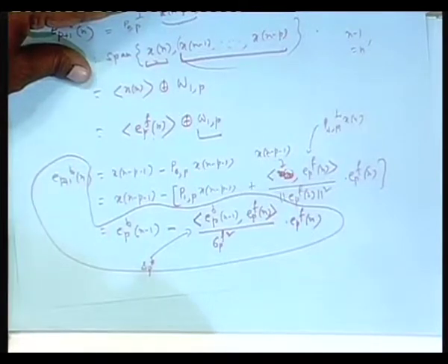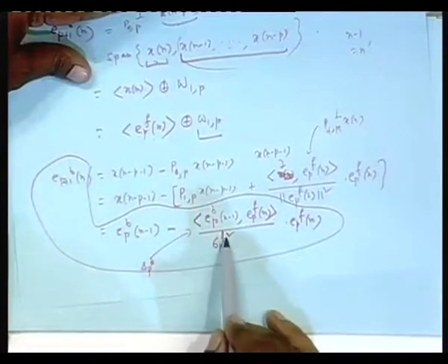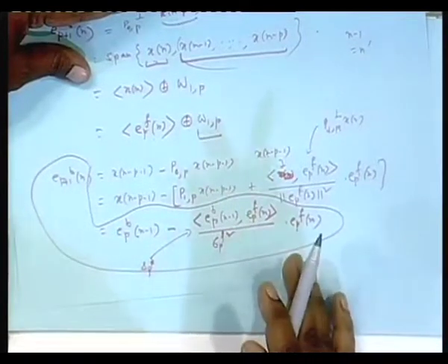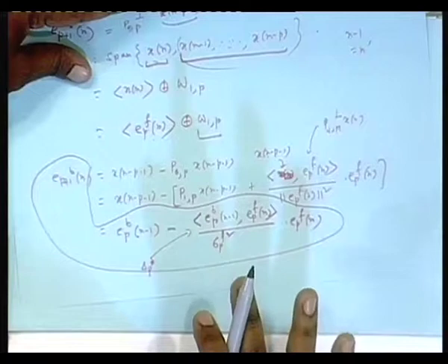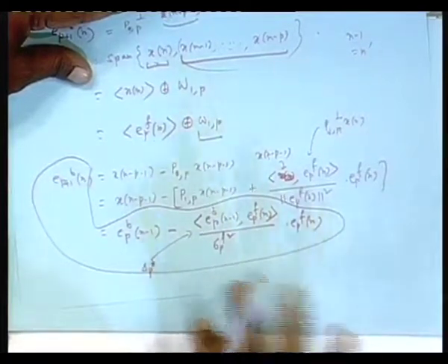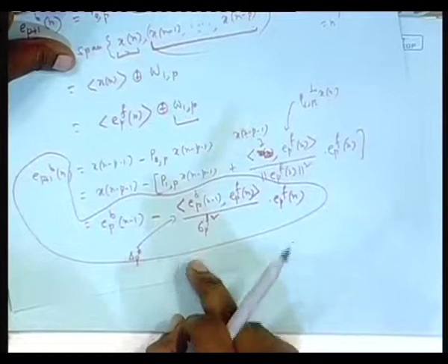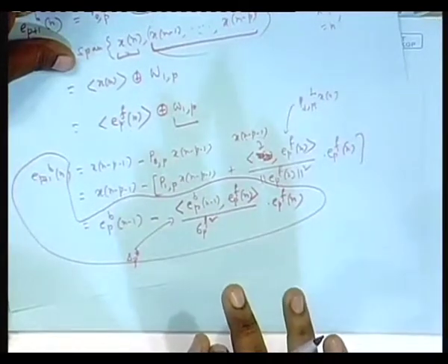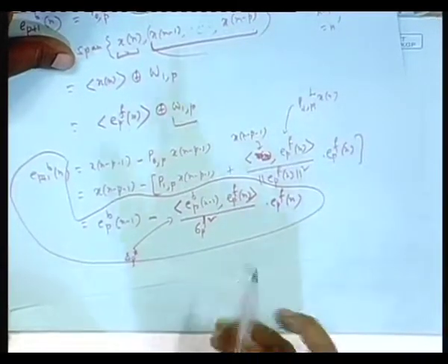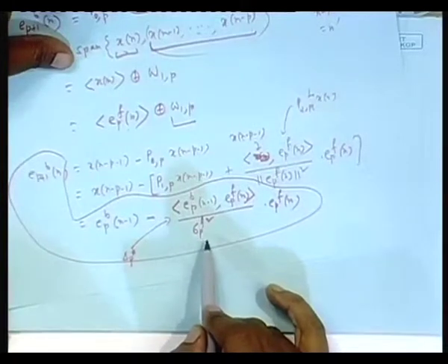Okay. We will show that sigma p f square and sigma p b square are the same. We will prove it using induction and stationarity. The numerators of these two quantities may be different. One is the variance of the backward prediction error, and the other is the variance of the forward prediction error of the same order, but they are the same. That we will see. And both are real, because they are variances.